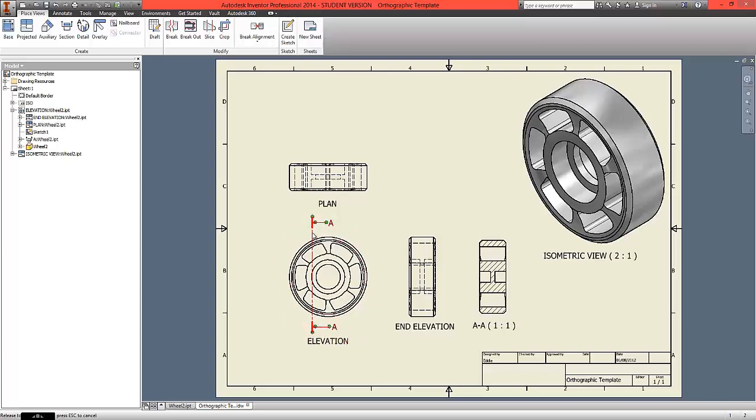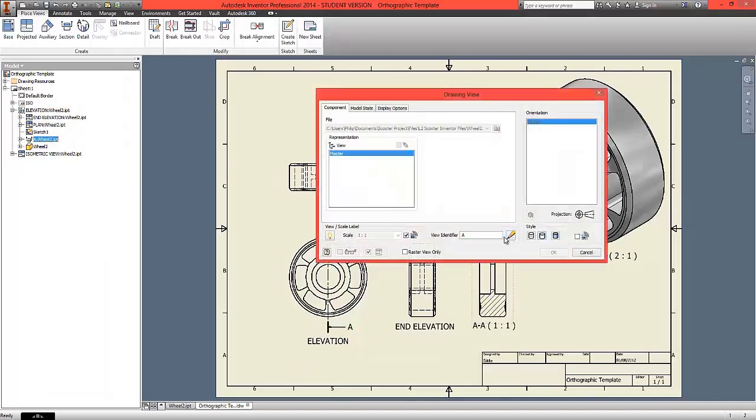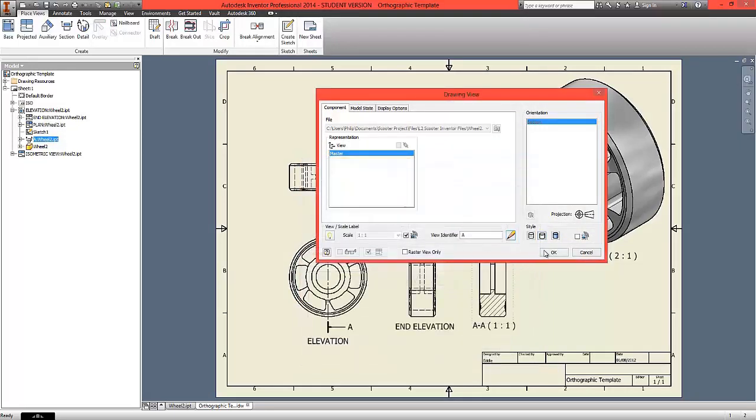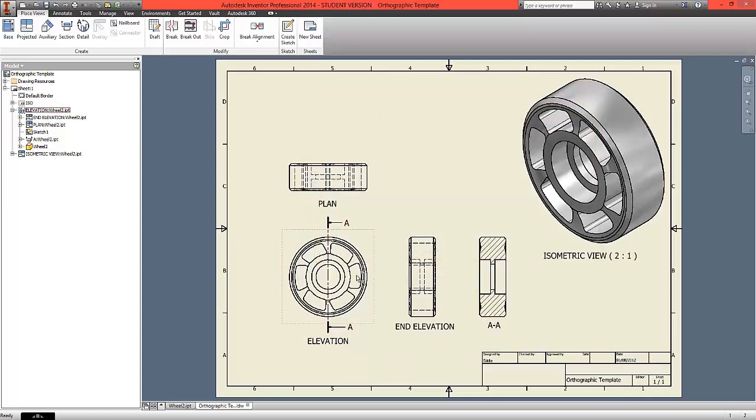And as you can see, if we drag the section line, the section view will update accordingly. What we can now do is position it as close to the middle as possible. What we're now going to do is double click on the section view and again, this time removing the scale, to simply leave the letters AA showing the section view.